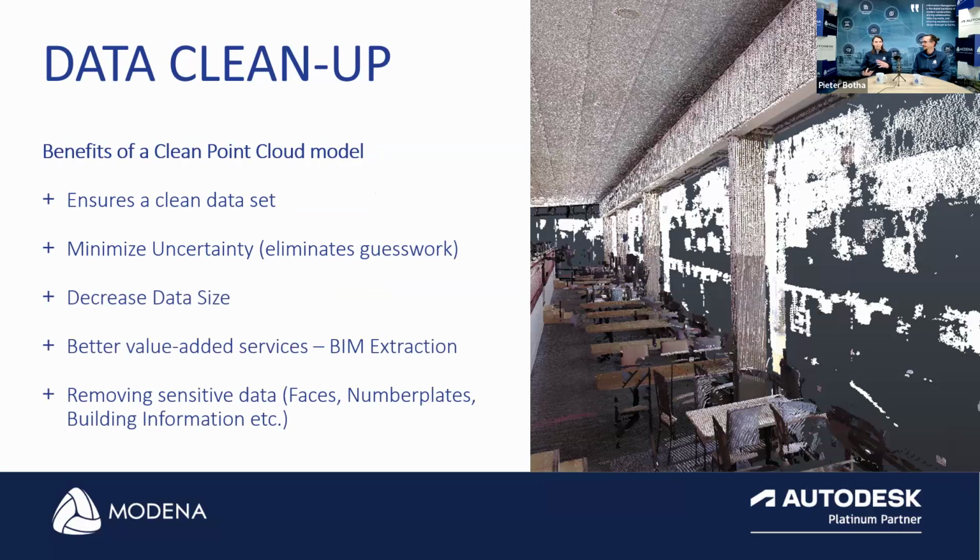Is this a pipe? Is this a reflection? Is my bathroom actually on the other side? No, it's scanning through a mirror. And then obviously to decrease the data size at the end of the day, and then better value added services. So for BIM extraction, the cleaner point cloud you put in, the better product you're going to get out at the end of the day.